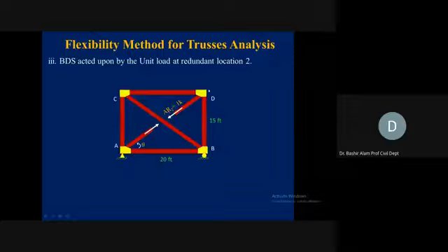Now, how can we find out the member force CD now? Look, its horizontal component will be leftward directed and vertical will be downward directed of this 1 kip. Already you have the components cos theta and sin theta, so you can find their magnitudes now. Its horizontal component will be balanced by the force in member CD. If it is leftward directed, here it will be rightward directed, means towards the joint, and towards the joint means member CD is coming under compression.